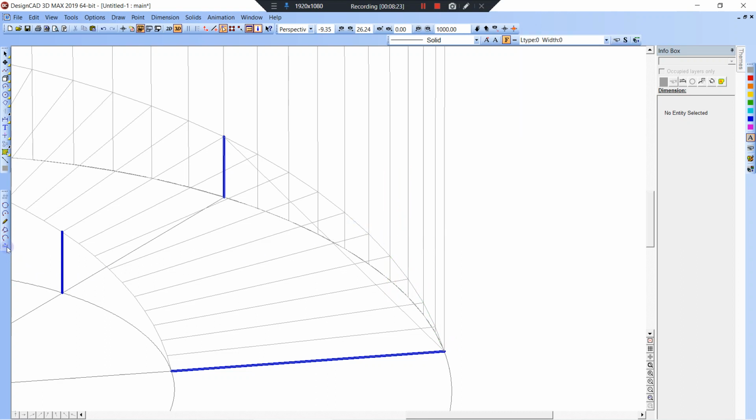Maybe the way you do it, let's draw an arc here. Maybe I could set this on the wall. Specify the radius. Let's go 12 feet, enter. Well, you already know it's 21 feet diagonal, so that's pretty close. I would go 11. Let's go 11. So K. Oh, what happened? F3. Radius. So that's an 11-foot radius, and then F3.